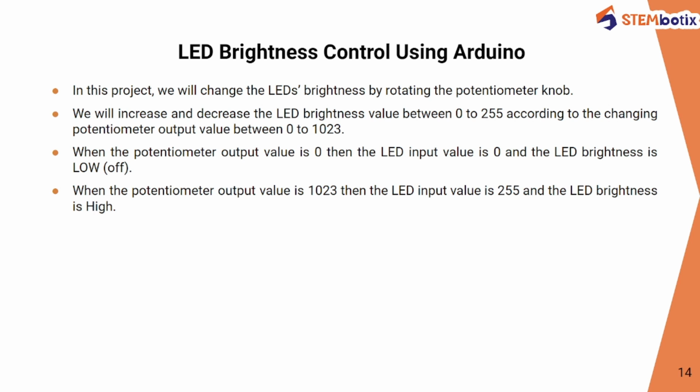Now the potentiometer is here going to perform as an analog device, which is going to change its value from 0 to 1023, means it will attain all the in-between quantities from 0 to 1023, giving output as the change in the LED's brightness, also from 0 to 255, means from lower value to its higher value, and also in between lower and higher.